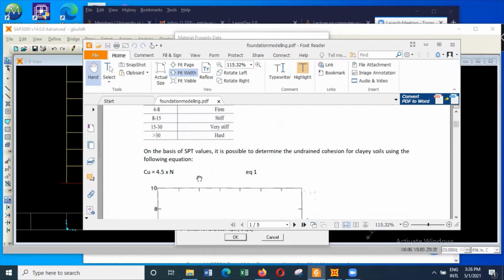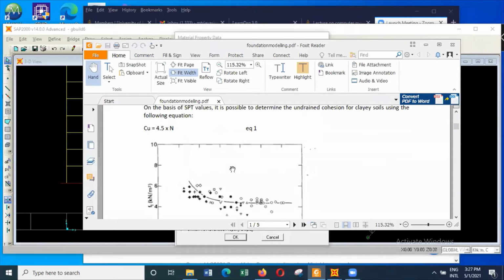You should have reasonably strong soil. So let's consider that we have something like laterite soil, which allows us to go for a raft foundation, and the water table is about 1 or 2 meters below the existing ground level. We are going to consider that this laterite soil will behave primarily as a clay soil, and so it's the undrained cohesion.